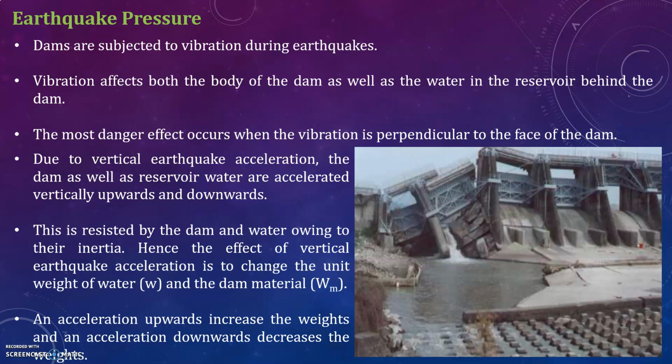Whereas for hydrodynamic pressure of water, the horizontal acceleration of the dam and the foundation towards the reservoir causes a momentary increase in water pressure since the water resists the movement owing to its inertia. The additional water pressure over and above the static water pressure is known as hydrodynamic pressure. So this is about earthquake pressure.